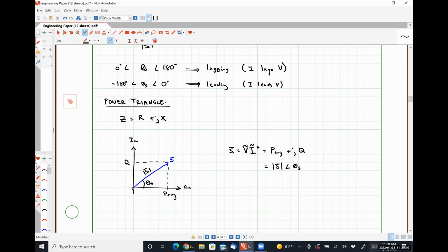which means it needs a 15 amp breaker to control it or whatever. That 15 amps is 125% of the ampacity of the wire or somewhere close to it. There's an extra 25% safety factor built in, right? What was the other one?